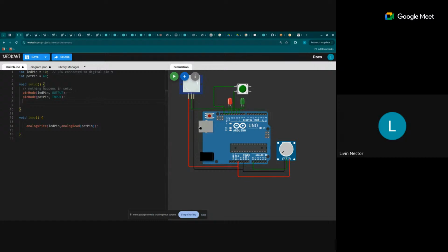So there is this USB over here, right? When you connect this to a computer while programming, actually the serial communication happens with this RX and TX pins, and it can also be done with the serial monitor, that is through this USB. So while you are developing, the serial output will also be transferred to your computer through this USB cable. Usually we use that to debug our code.